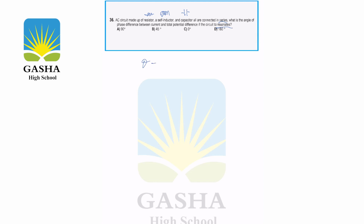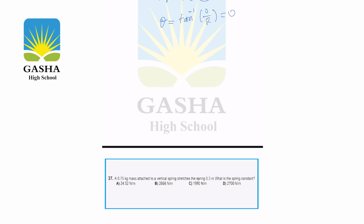We already know that the phase difference can be found by using this formula when they are in series, and during resonance, we already know that XL is equal to XC. So when XL is equal to XC, then the numerator of the fraction will be equal to 0. So that makes θ equal to tan inverse of 0 over R, and that will be equal to 0. So 0 is the correct answer, which is choice C.